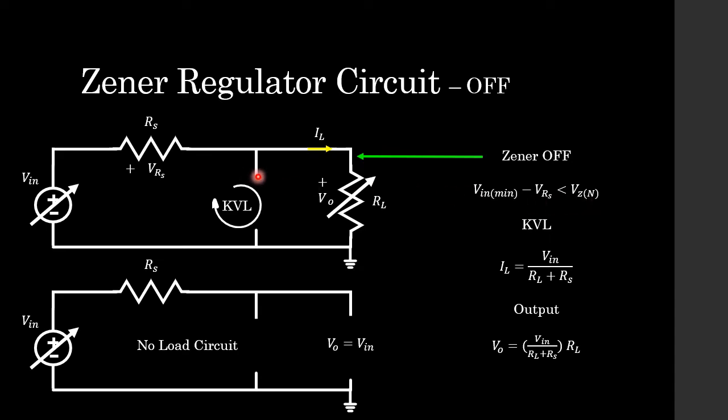So we don't have this Zener diode being broken down, therefore we replace it with an open circuit, and of course it's not being forward biased because the anode is not connected to this voltage being applied here. The anode is connected to ground.